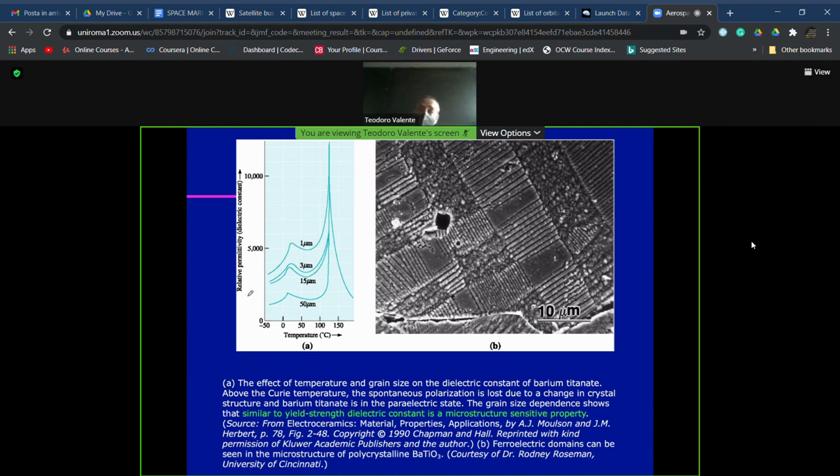If this impulsive load is applied on a piezo material, which has the property to have a very fast response, it can work well for hundreds of hertz, it gives back a voltage. If we measure the voltage and we have a graduation scale, we can calculate which was the load transferred by the impact, the impulsive load.